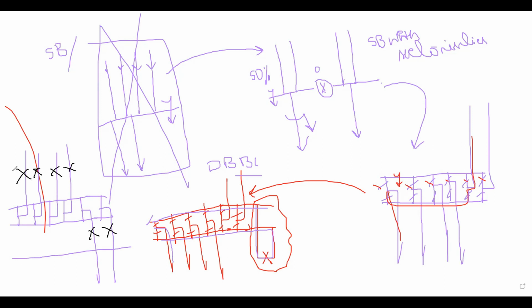Suppose if the breaker fails, the power will fail, right? So what we do is, let me draw it. This is the bus coupler, and this is one more sectionalizer, which is connecting to this bus. Now we are taking a bypass.